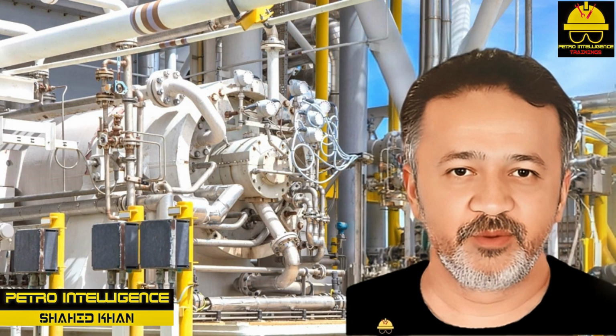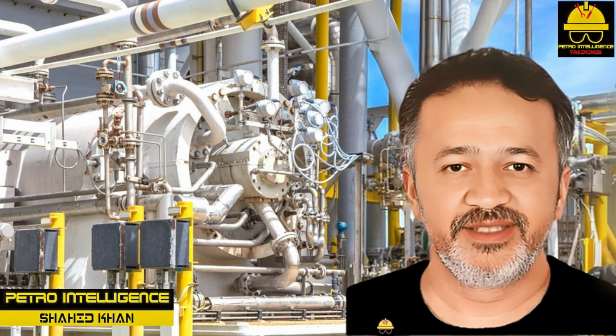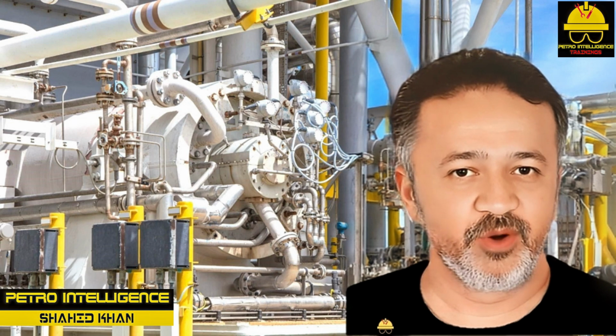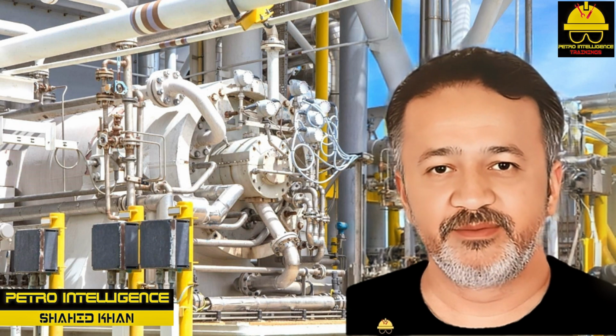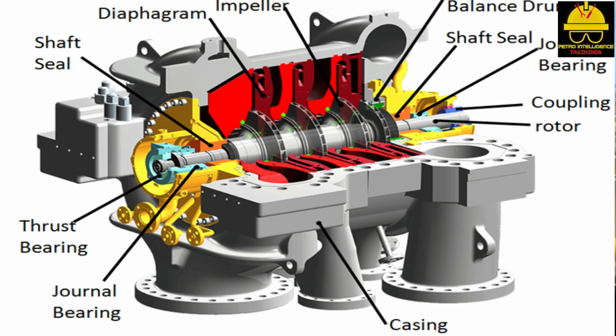Most centrifugal compressors are designed to operate at speeds in excess of 3,000 RPM. Recent advances in technology have resulted in the development of a centrifugal compressor that runs at speeds in excess of 40,000 RPM. Centrifugal compressors can be single-stage or multi-stage. Single-stage compressors, as shown in the picture, compress the gas once, whereas multi-stage compressors deliver the discharge of one stage to the suction of another stage.